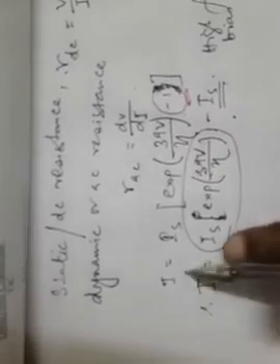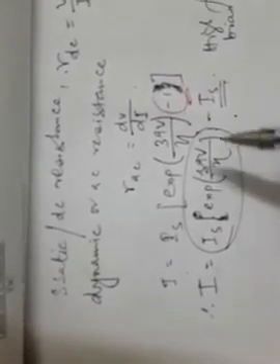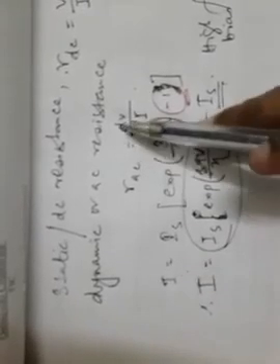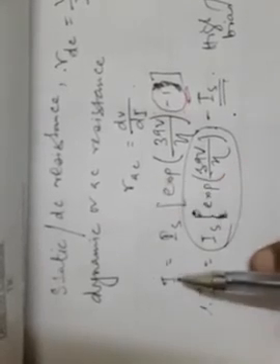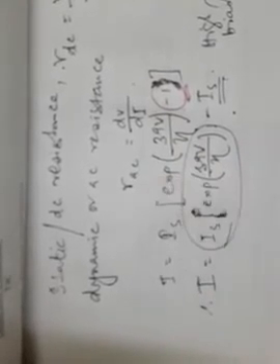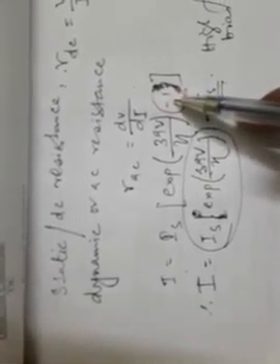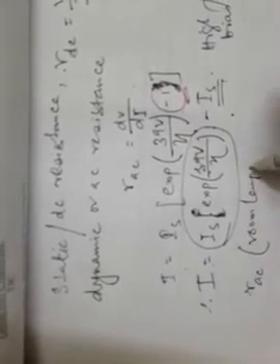So this equation will be simplified during the forward bias, and if we differentiate this equation to find dV/dI and accordingly this dynamic or AC resistance RAC, that means differentiating with respect to I, neglecting this one during high forward voltage, we get RAC at room temperature, because we have derived this equation considering T equal to 300 K, that means room temperature.